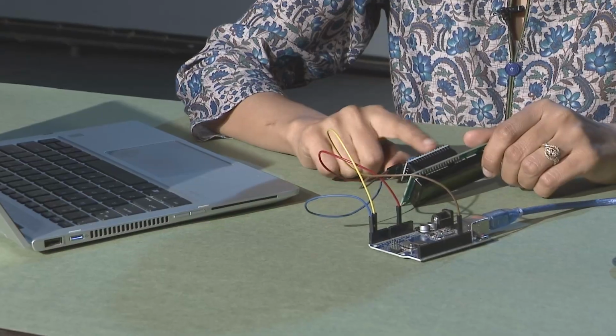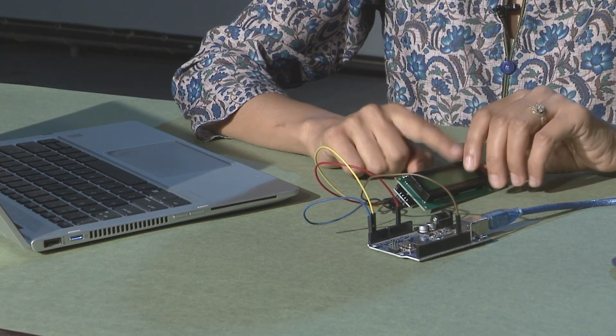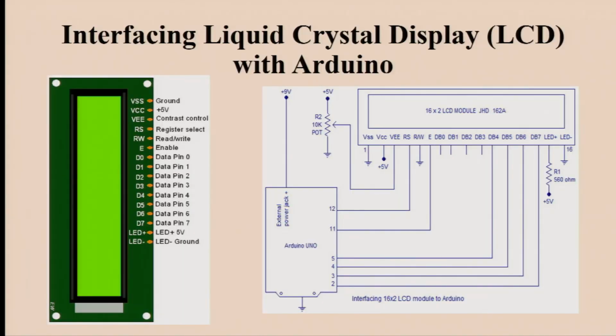In case you are not utilizing this board and you are making all the direct connections as I have shown you in the first circuit diagram, in that case you will not utilize this LiquidCrystal I2C library, rather you will utilize the direct LiquidCrystal library only. So, in our case, since we have combined these chips, we will be utilizing both the libraries together.